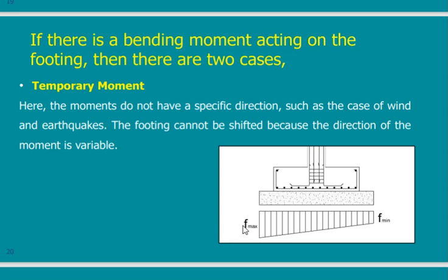Let me say it first. If this footing is subjected to two forces, the normal force, the stress of the normal force, you can say that it is something uniform, because normal force divided by area gives us a constant stress. Moment acting on an area will induce compression on one side and tension on the other side. But the normal force due to the column is always compression.